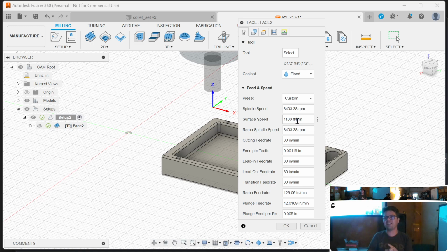So one of the warnings I have about Fusion 360 right now is if you don't muck with settings, it will auto-update them for you a lot. Don't always trust those though. One subtle slip up of where you're clicking or typing a number in wrong can get it different on one operation, and then if you go edit it on the tool, you can't be sure it changed on all the other places. There's 3 little dots here.